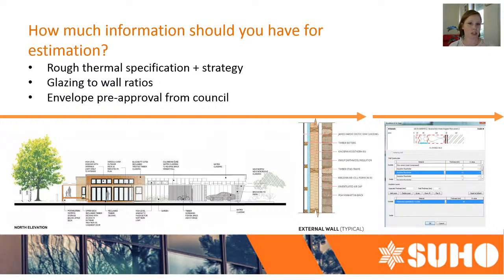So I mean, this could change slightly depending on what products you're using, but we get a very good idea of the different layers within the side of a building and how well that's performing. These are different scenarios, but essentially it can show all the air layers in a wall and how it's going to perform. Do we want a ventilated cavity or a still cavity? Do we need certain sorts of membranes within that?